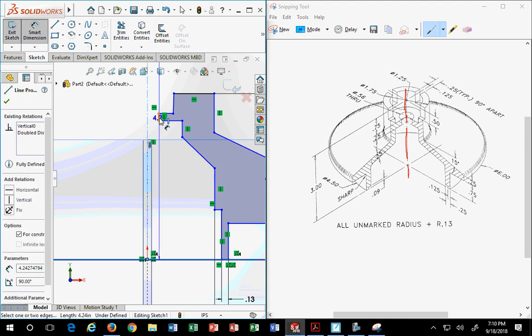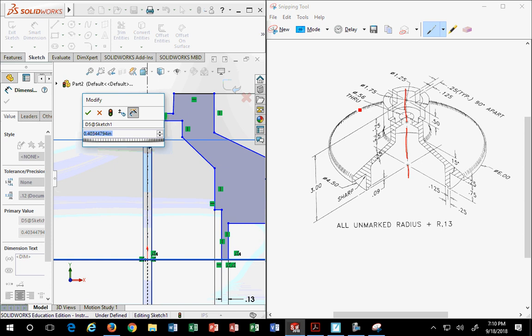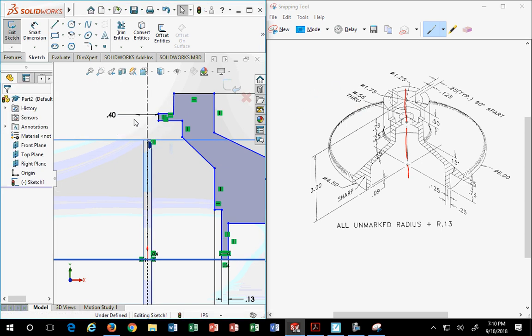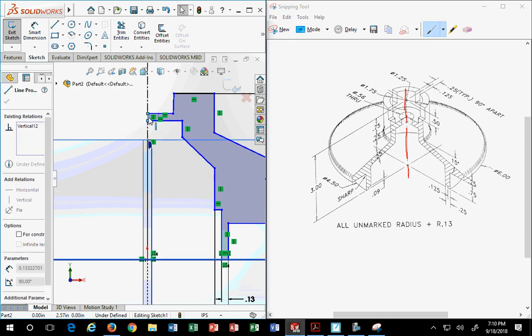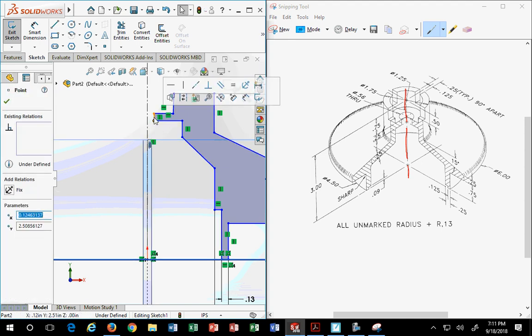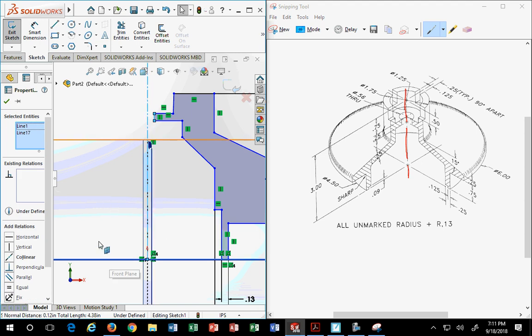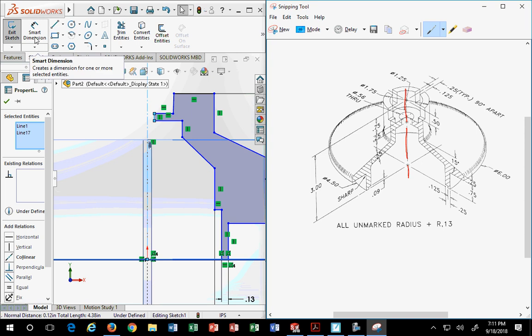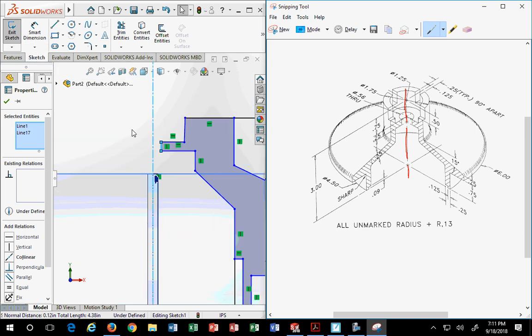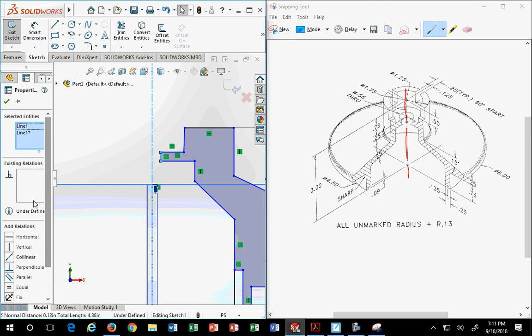So if I go from here to here, this inner hole diameter, now that specifically gives a diameter. It says diameter 0.56 through. You notice that? That's probably the only object I don't want cut through, to be honest, only because I want to actually make it a hole. Why? For the same reason I've suggested using the hole command in the past. So that when you do your detail drawing, you'll have this detail drawing option. If you make it part of your feature, you'll never have that as your option. You'll manually have to do it. So I'm actually intentionally picking my center line and that object so I can do collinear.